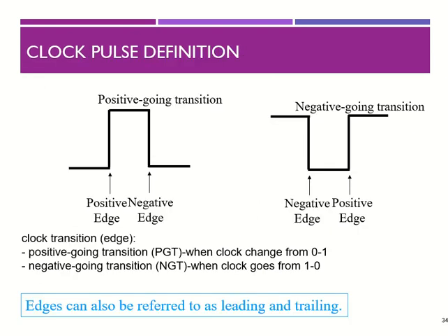This one is explaining in more detail. So this is positive, this is negative, and for the negative transition, this is falling and this is rising. You need to understand whether it is positive or negative going. But usually we only focus on the positive going transition rather than the negative one. But it can be any situation depending on your declaration.